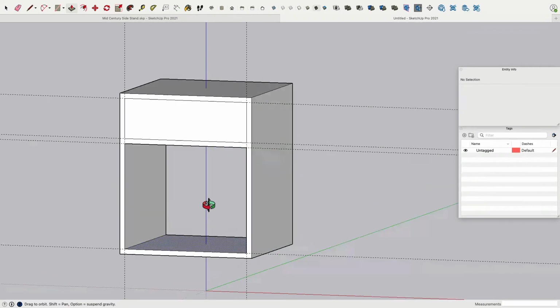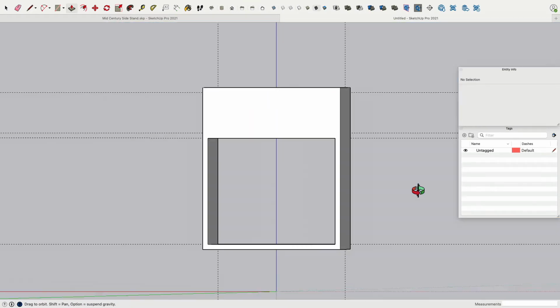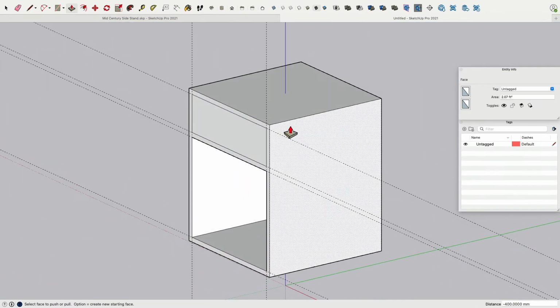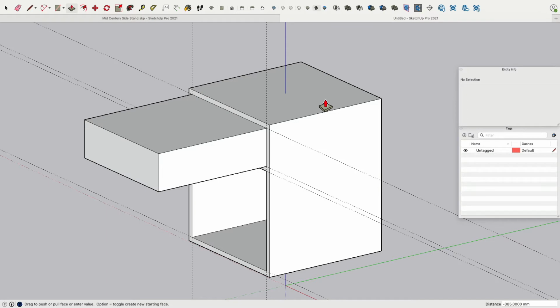There, on face, click, and then it cuts it through. Very nice. The whole object is 400 millimeters, and the back should be 15 millimeters. So this will be 385. So you go minus 385. Oh, and you see now I typed in minus while it said minus.